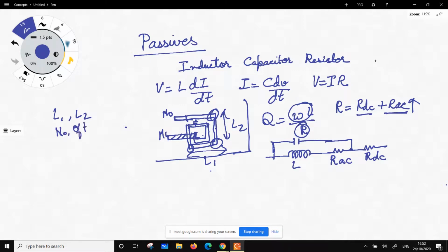And we said that we will restrict only two, right? And usually L1, L2 is in the range of like 60 to 180. Whatever inductance you want, you will get roughly in this range. So L1, L2 will be equal, so we will make it a square. That means the condition is L1 is equal to L2. So it will be a square. Number of turns we will restrict to 2.